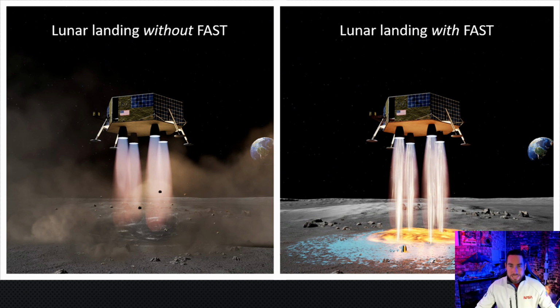Basically, this company called Maston, when they fire the retro rockets to bring the lander in, is going to inject ceramic particles into the rocket engine nozzle. This builds up a coating over the regolith. It injects the ceramic, which starts coating the regolith, and it builds up and the particles adhere to each other. It creates a hard landing pad that has much better thermal and ablative resistance.